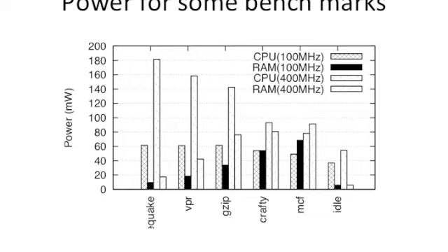Okay. So what that tells me is that clearly some component, because as you all know, most of you have done the digital VLSI class, the dynamic power dissipation is proportional to frequency, CV square. Right? If power was completely dynamic power, then you would have expected the power to quadruple. But power is not quadrupling, which means there is some amount of power which is independent of frequency. And that is not that hard to believe, because you have static power, which is power due to leakage and so on.